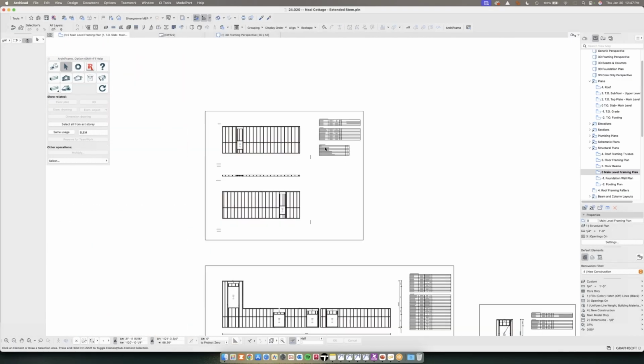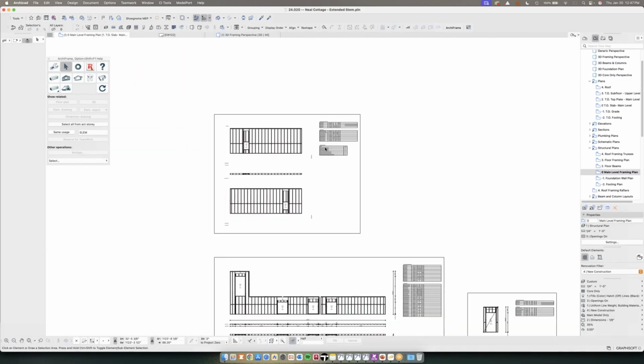And do you actually, with the sheathing, have that turned on for being able to show that with details or wall sections, etc.? Yeah, so in the sections and details, it shows on there for sure. But just for simplicity and cleanliness, I don't show it on these plans. Every contractor I found does sheeting their own way. So in my experience, they appreciate the ability to see the wall framing, especially in a complex wall.